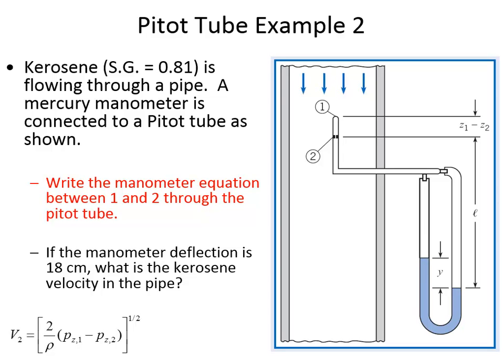A propeller spinning around? Yeah, sure. Like a paddle wheel? Yeah, they could. But remember, it would have moving parts, and the pitot tube doesn't. So anytime you've got a moving part, there's potential for breakage.